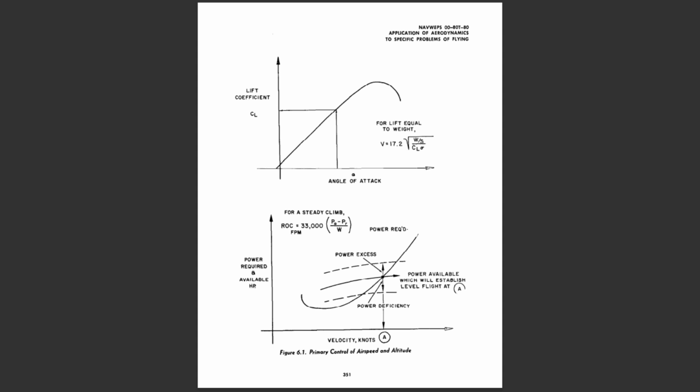With some configurations of airplanes, low-speed flight will bring about a low level of longitudinal stick force stability and the possibility of low airplane static longitudinal stability. In such a case, the feel for airspeed will be light, and may not furnish a ready reference for easy control of the airplane. In addition, the high angles of attack common to low-speed flight are likely to provide large position errors to the airspeed indicating system. Thus, proper control of airspeed will be enhanced by good attitude flying or, when the visual reference field is poor, an angle of attack indicator.